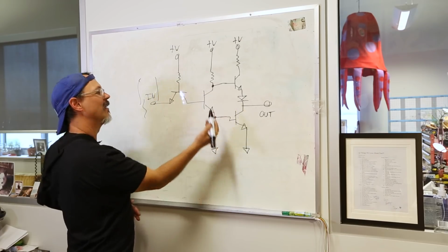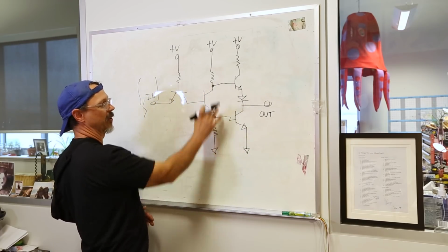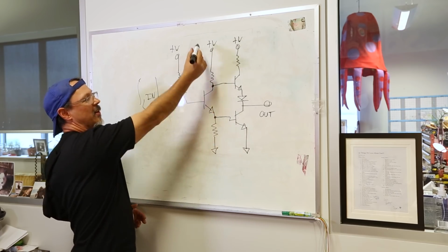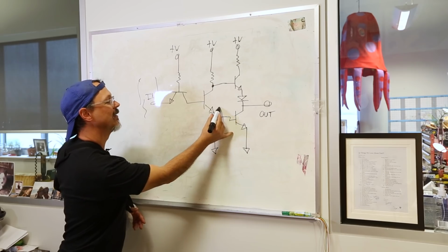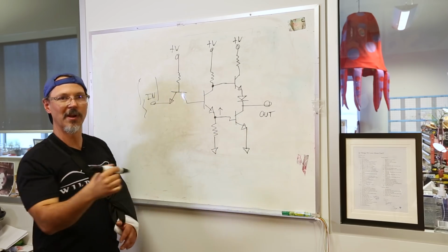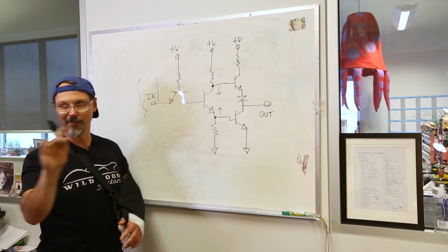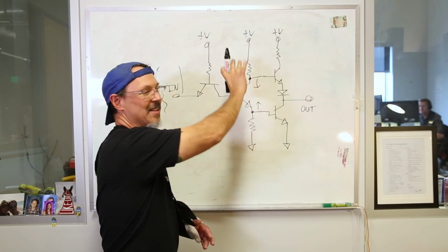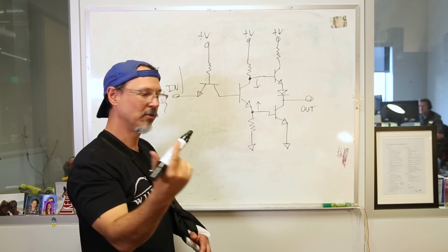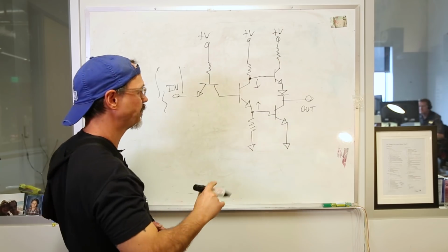When this guy is on, this resistance becomes low, and so the current increases through the concertina section. That has the effect of raising this voltage with respect to ground and lowering this voltage with respect to ground. Now, remember, as I'm saying that, the voltage across the component itself is increasing, but with respect to ground, that point in the circuit is going down, okay?